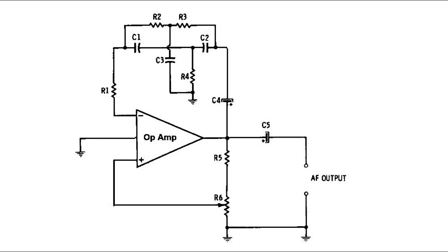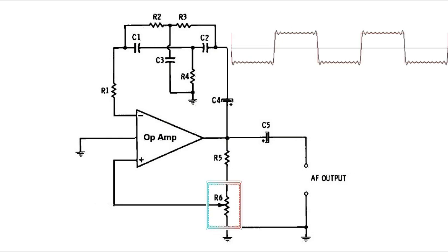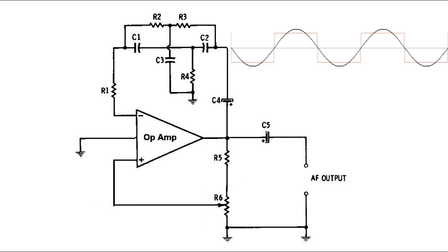The inclusion of positive feedback by means of the signal divider R5, R6 results in this very sharply tuned amplifier oscillating with the frequency FR. When the potentiometer R6 is adjusted to the level where the circuit merely starts to oscillate, output signal distortion is found to be minimal.